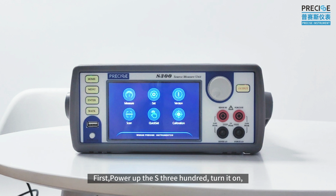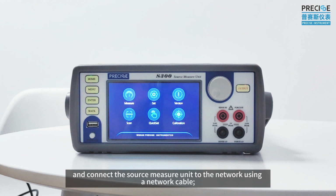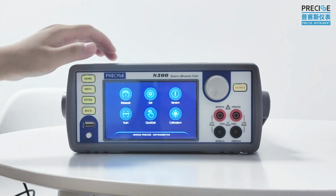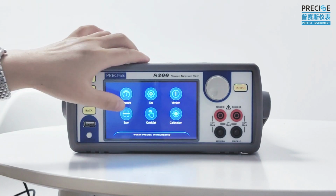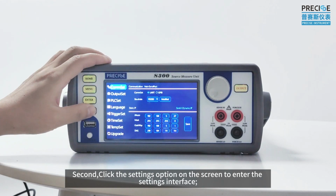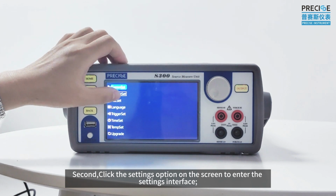First, power up the S300, turn it on, and connect the source measure unit to the network using a network cable. Second, click the Settings option on the screen to enter the Settings interface.